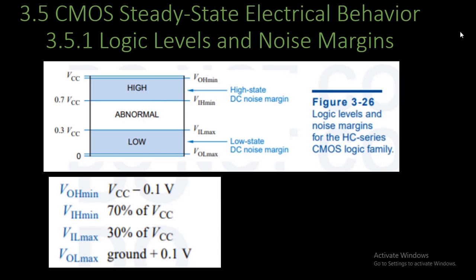Regardless of the voltage applied to the input of a CMOS inverter, the input consumes very little current, only the leakage current of the two transistors' gates. The maximum amount of current that can flow is also specified by the device manufacturer. IIH, the maximum current that flows into the input in the high state. IIL, the maximum current that flows into the input in the low state.